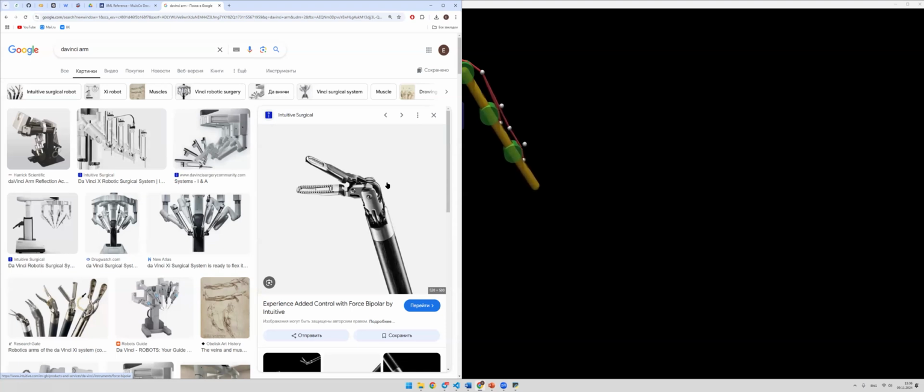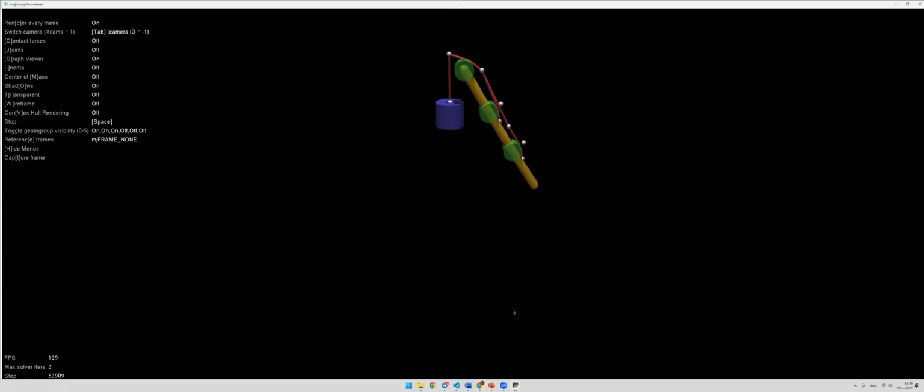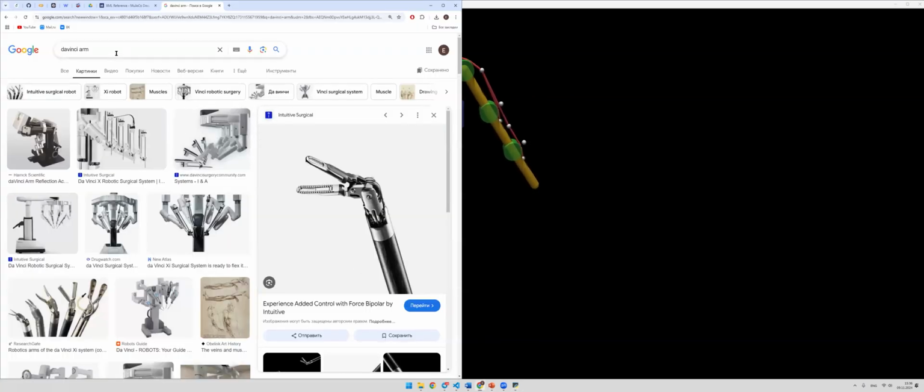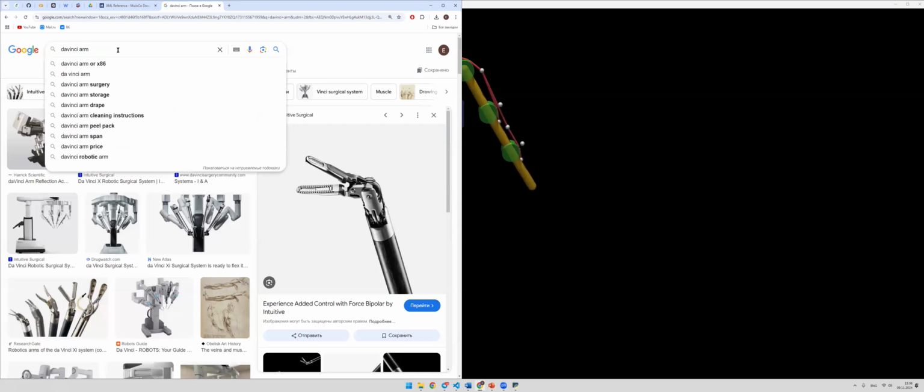The advantage, as I said, is that it moves the motor away, makes the end effector smaller, decreases its mass and inertia, and makes it move in smaller envelopes. But the disadvantage is that, of course, the mechanism is quite complicated. The designs of these tendon-driven systems are quite tricky.